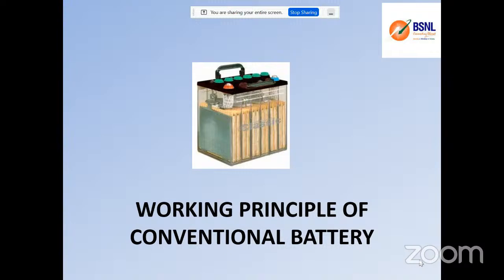The idea behind it is that the load is always connected to the battery backup, and the battery backup is always connected to the external power supply with the help of the SMPS power plant. So at any point of time, the load is maintained with maximum uptime, without any interruption from the external power supply, right? This is the purpose for which we use batteries in our telephone exchanges and almost all places.